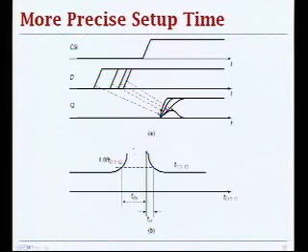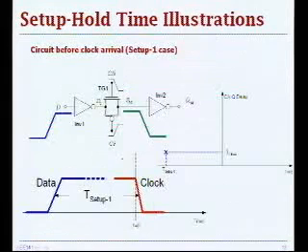And this is basically, now we can explain this by looking at the clock to output delay as a function of data to clock offset. So let's take a look at this illustration. Let's assume that our data signal arrives sufficiently long such that I will have no problem catching this at the output over here. And that corresponds to this point indicated in this graph.